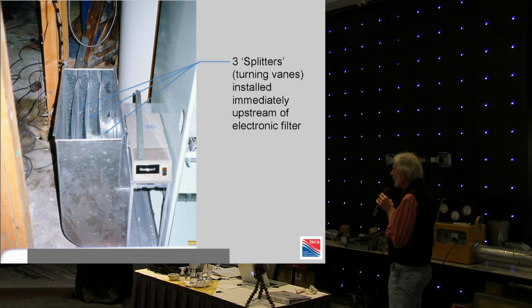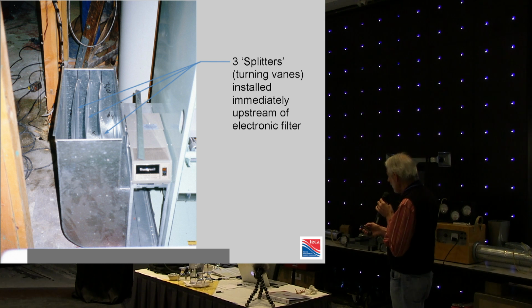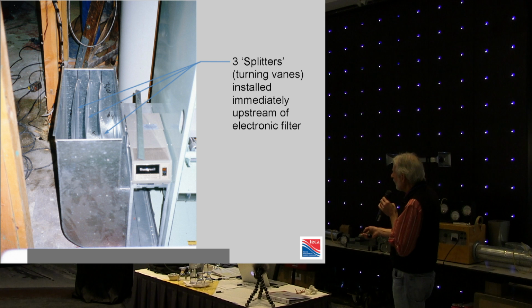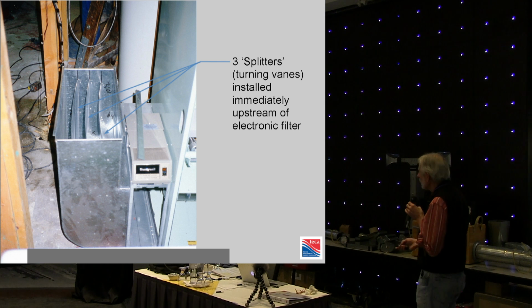Here's an example of a splitter, which is even more sophisticated than a turning vane, because the vane actually starts right here and goes all the way through. You can see the little spot welds here. It's guaranteeing that the air proceeds in a perfectly streamlined pattern into that filter. It has to be. It's non-negotiable.